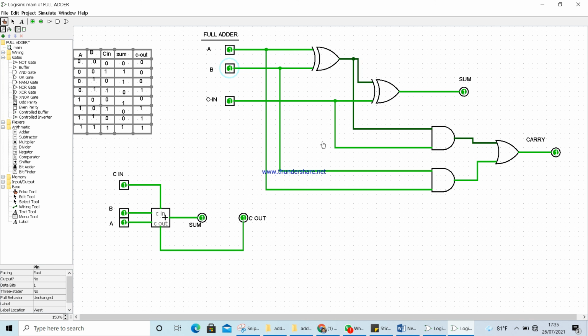So from these two circuits, it's confirmed now. So this is what happened when you use 3 bits input to a full adder. This is what we call a full adder. So if you input 3 bits, those 3 bits are added by these circuits, and it will result in 1 and 1 here. Actually this represents the carry is 1. It means there's 2 inside of this, the number 2 is hidden inside of this, and sum is 1.